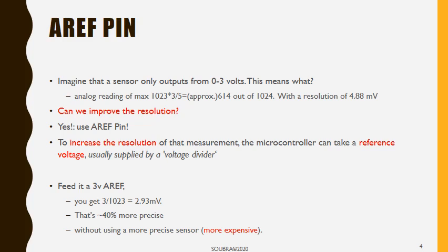In case of 3 volts. Come again. So in case of 3 volts, remember, the voltage that you have represents the physical signal that you're trying to follow. So in case of 3 volts, your physical signal could be anything between 0 and 3 volts. Make sense? It can take any value between those two. The idea is how to map those values to some numbers on the digital side. Get it? So this is what you're trying to do.